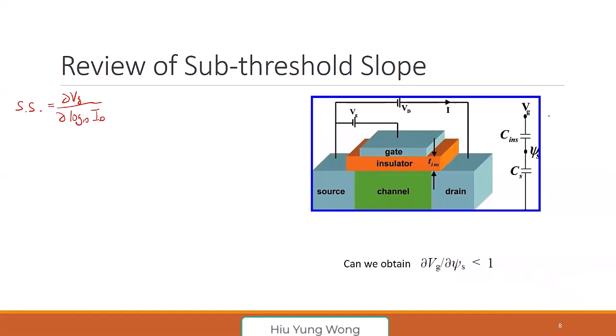Now let's look at this again. For every device, we have an insulator, I showed you before. And then you have the substrate. This one can be the depletion capacitance, but we lump them together because there may be fringing capacitance. Your transistor is not perfect. You don't only have the vertical depletion capacitance. And also when your drain bias is high, it is not uniform. So let's just call it CS.